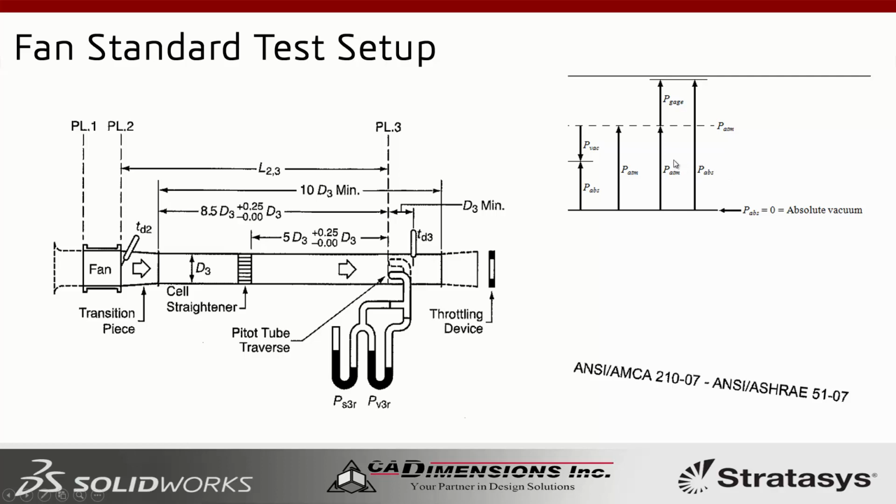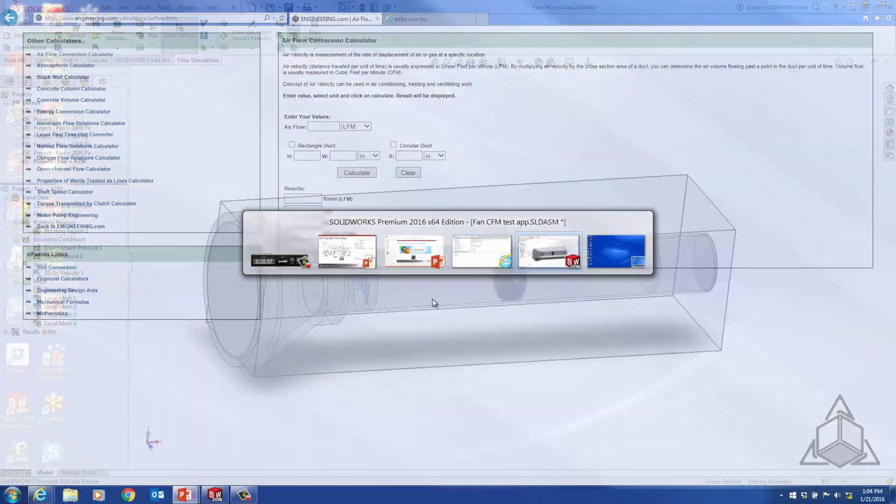So if 1000 Pascal is what your standard is supposed to be set to, you take your P atmosphere, typically 101,325 Pascal, and add 1000 Pascal to that, which gives you the P absolute. That's the value you will set within the analysis to meet that gauge pressure. This will make more sense when we look at the model, which we're going to jump into right now. So let's switch to SolidWorks.